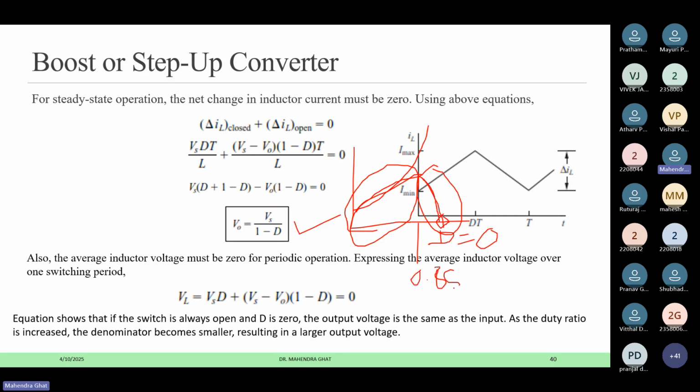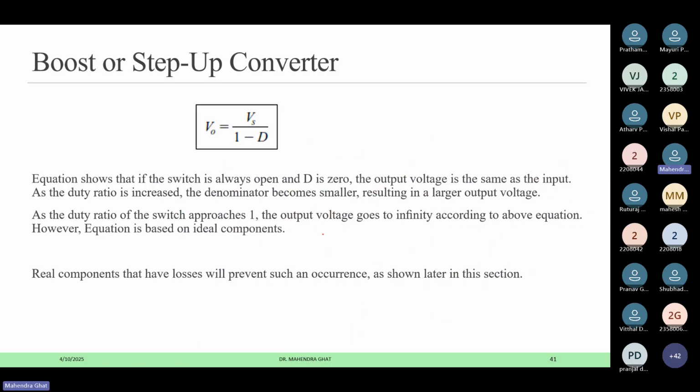That also depends on the inductor resistance and all these things, but a rough range is from 0.85 to 1. We cannot use the boost converter to boost the output voltage. So that is just a rough consideration, because we will end up in this region where the output voltage is actually decreasing. So that was the boost converter.